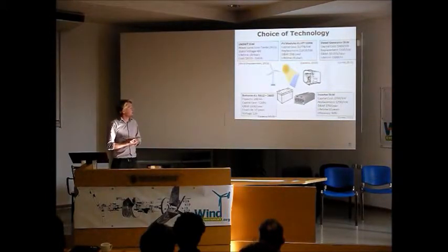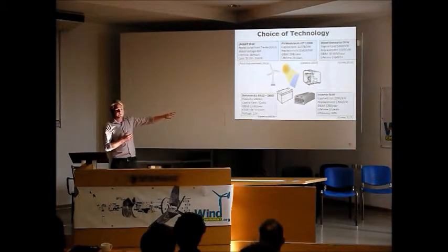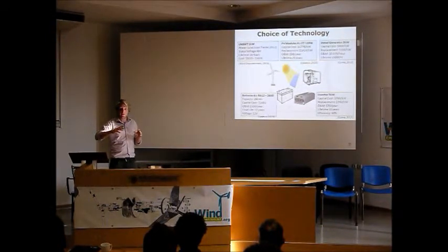For the choice of technology to include in the system, we did a hybrid system with wind, solar, diesel, batteries and inverters. In Homer you need to know the capital cost, the replacement cost, the operation and maintenance cost and the lifetime for each of those components, and you want those to be as accurate as possible. The lifetime or the operation and maintenance costs can really change the economics of the project over 20 years. So this needs to be gathered, ideally first-hand in country from local suppliers.